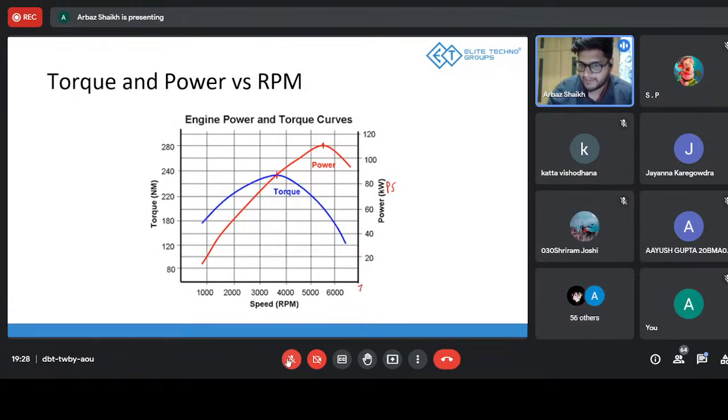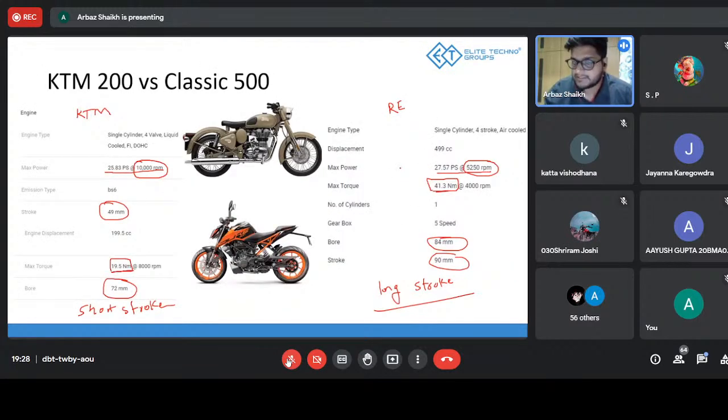If I write this to be 7,000, then there'll be one for 8,000, 9,000, and then one for 10,000, correct? Somewhere around here there'll be 10,000. And if I draw a line for 25, it will look something like this. And over here, the power will be max for a KTM 200. But if I talk about a Bullet, it's going to be 43 Newton meter at 4,000 RPM.